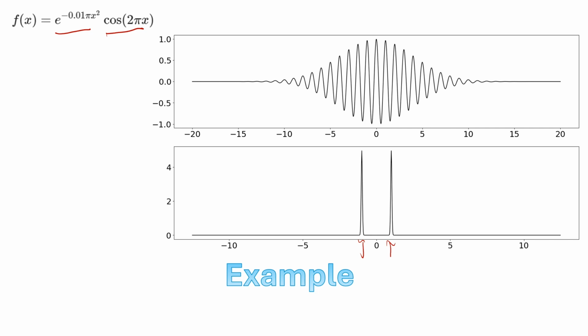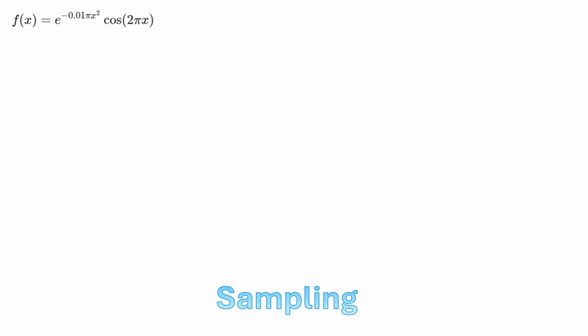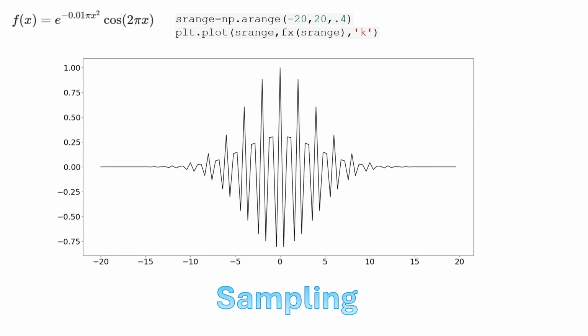So here we've sampled this function relatively densely. This is also done with discrete analysis, but this is with 1,000 samples over 20. Now, for this particular function, the bandwidth, b, would be about 1. So the Nyquist sampling rate would be 0.5. The delta x would be 0.5. Here we're sampling at 0.4, so you can see these are now discrete samples of the function, and we see the jagged curve. We've sampled about 20% over Nyquist.